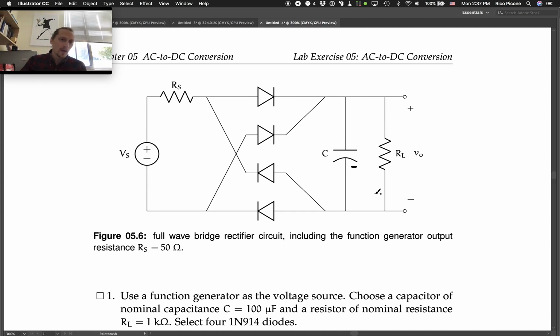The reason it's okay is the way that we're flipping back and forth. So remember, when this is positive, we're going to be charging up the capacitor this way. There'll be a drop across that way. When the source is negative, then this will be higher, and it'll still charge up in the same direction.